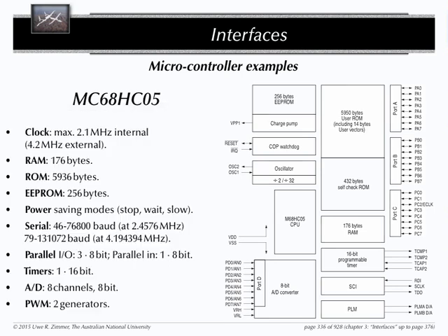What do you have? 2 megahertz, 176 bytes, a few power saving modes, a bit of serial connections, I/O bits, 3 times 8-bit parallel, 1 timer, 1 AD channel, 2 PWM generators. And this was the state of microcontrollers for decades. A number of variations. You could also buy them, of course, from other manufacturers, but this is what they mostly looked like.